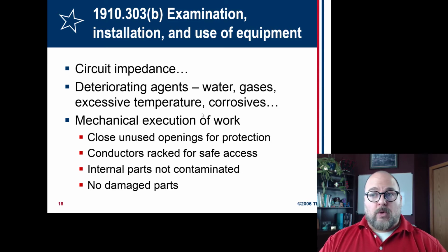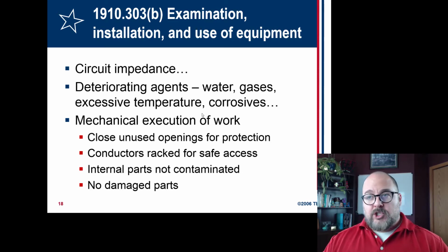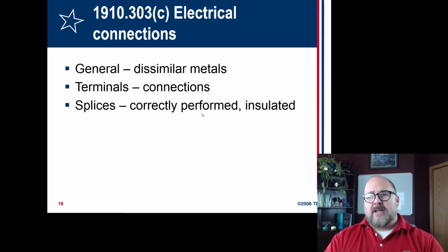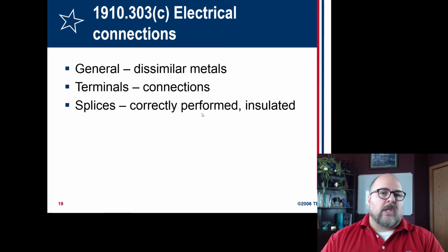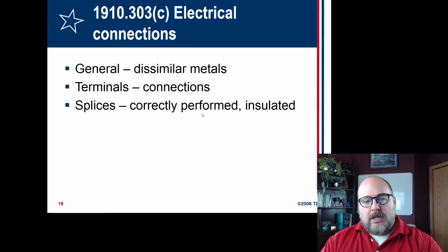And unless you have somebody who's qualified to repair it and test it and put it back into service, it should be replaced. I've cited that before with OSHA. You shouldn't have dissimilar metals contacting each other. We typically have copper lines, but in the olden days they had copper and aluminum, and you'd have special connectors, special systems for it. It's better if everything is just copper.